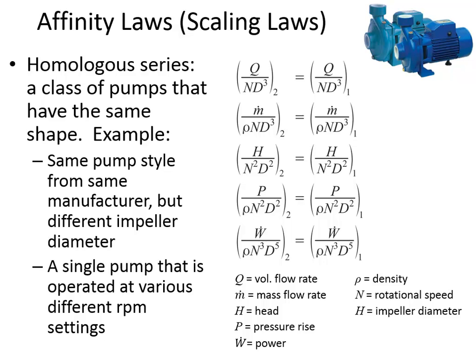But if you scale down that collision to a Matchbox car, it doesn't dent in the same way that a full-size prototype would. So that's a bad analogy, the Matchbox car to a full-size car. The same kind of mathematical principles that we were talking about in dimensional analysis and Chapter 8 from last semester, this is what this is picking up on. And it allows you to look at pumps and how they behave in different circumstances.